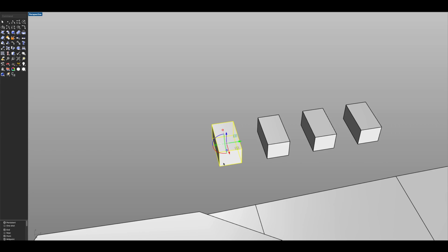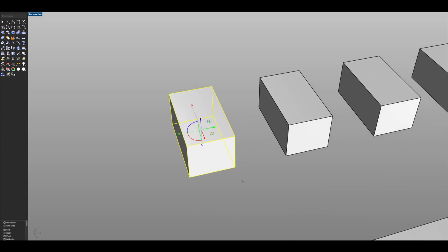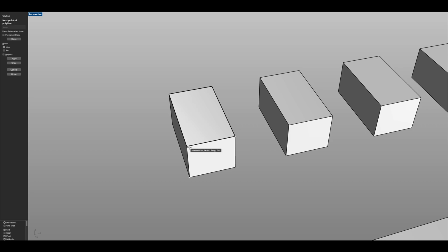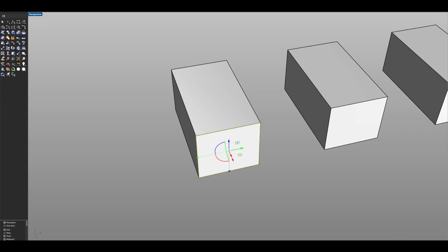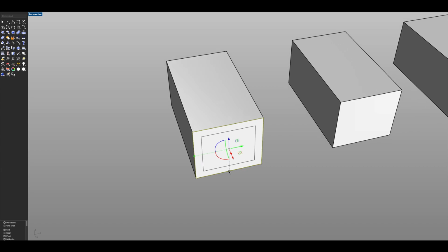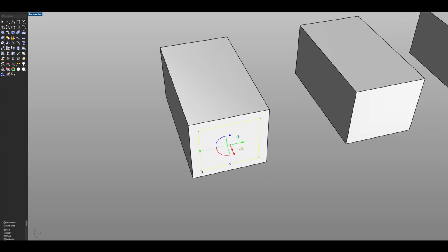Okay, so the first one we're going to build is our passage container, and to do this you want to draw yourself a line on this face, then CL to close. You want to select your line and then place offset, and the usual thickness of these containers is around 60 centimeters, so I'm going to go for 0.6, then simply click enter. Oh, hold on. Yeah, okay, you need to click the face to make it work. Now we can actually leave these as they are, and then we can select this inner curve here. Let's select its lower points, and I'm going to bring this down on the Z element by -0.6.